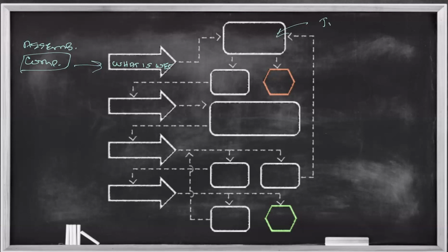Once we know what's wet, conversation for a different day, but next thing we do is what we call the restoration triage, which is evaluating cost, damage, and contamination to determine restorability. Again, had a great episode on that in Technically Speaking yesteryear. In one of our episodes last year, we dug into that conversation. But cost, damage, and contamination will establish, should I restore the material? Possible answer is no. Possible answer is yes, right? What is the restorability?